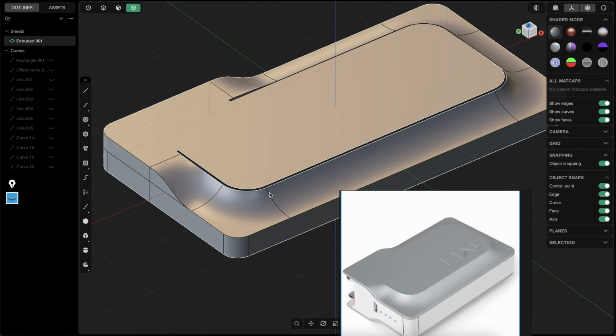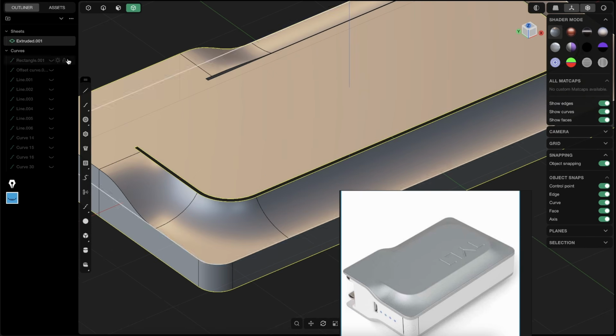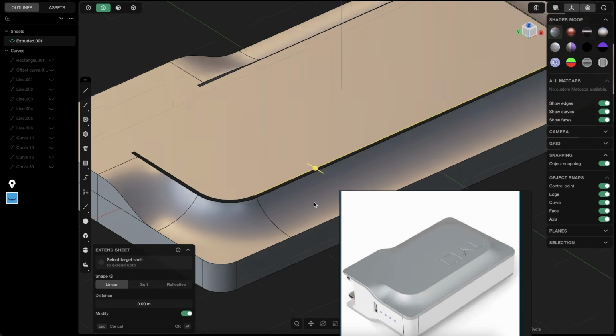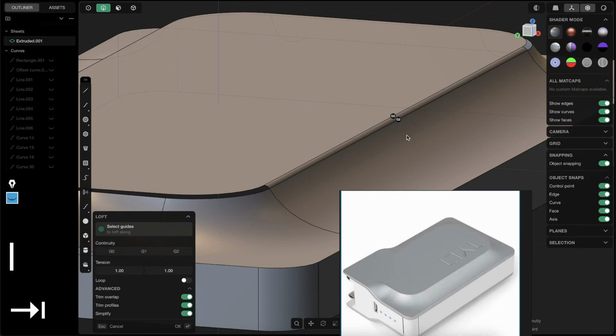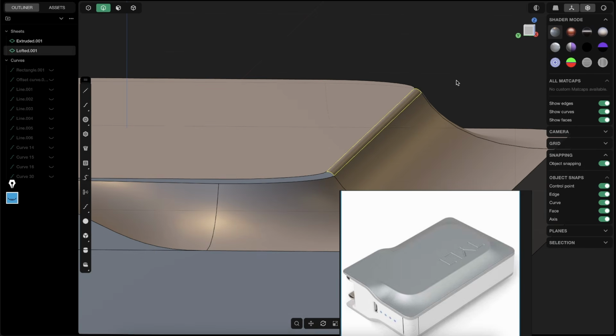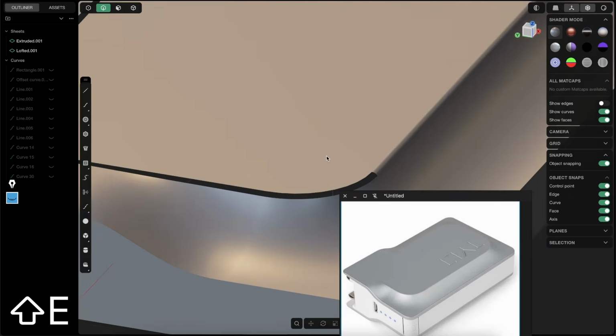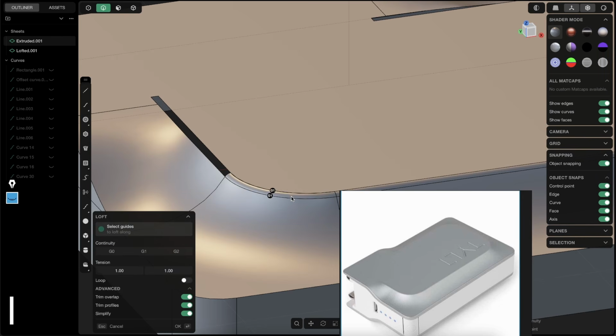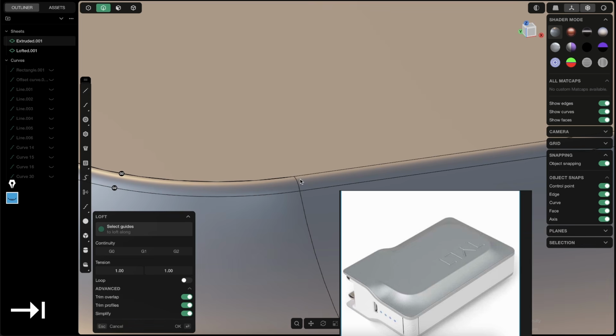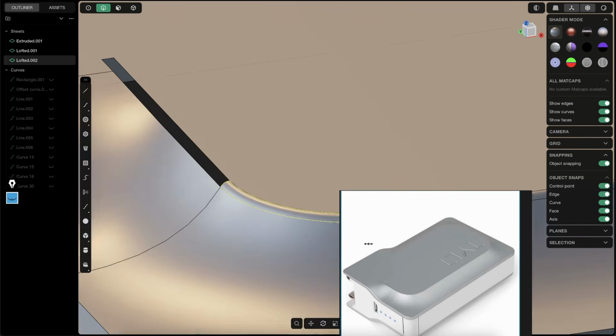And now we have absolute full control over the fillet with, again, surface modeling. So what I mean by that is, if you press 2, you can now select this edge and this edge and press L for loft and press tab. So you give it a nice G2 clean fillet. And now let's see, this looks perfect. And the same here, select both edges, press L, press tab for G2. And very important, shift click, so it's glued together and connected. So shift click, and like that.